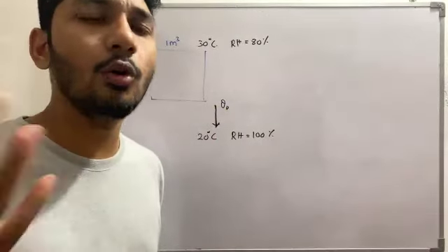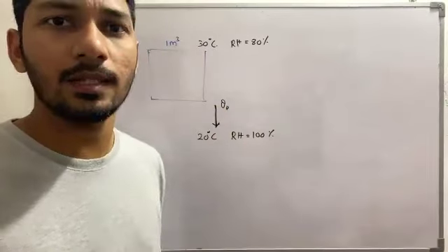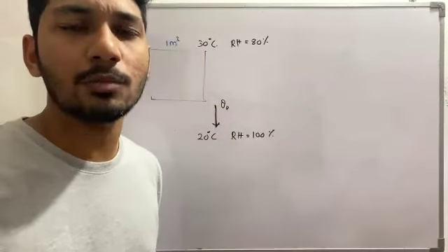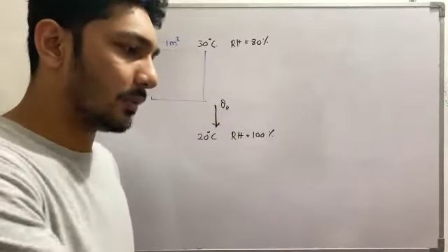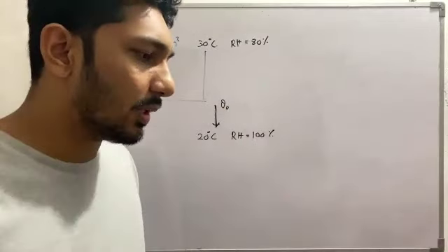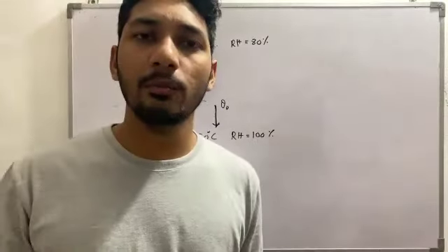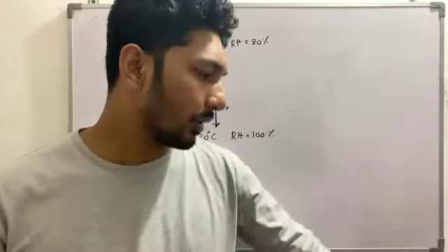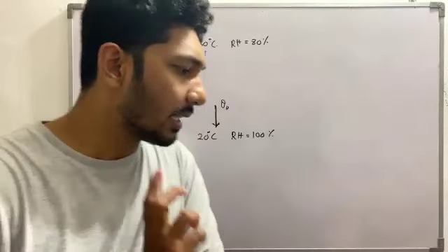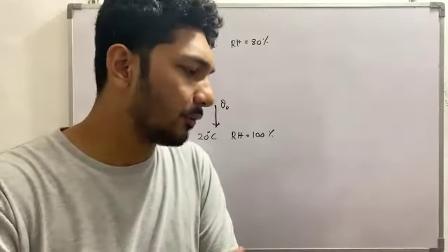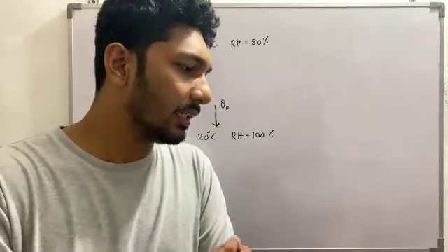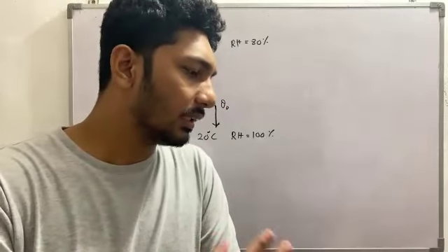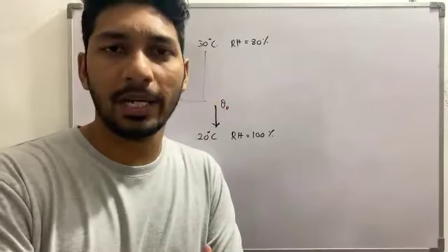How do you decide how much was condensed? That is using the maximum H possible. That is what you call the absolute humidity of the saturated vapor. So here it is given. Can you see that the absolute humidities of saturated vapor at 30 degrees and 20 degrees are 30 and 18 into 10 to the power minus 6.